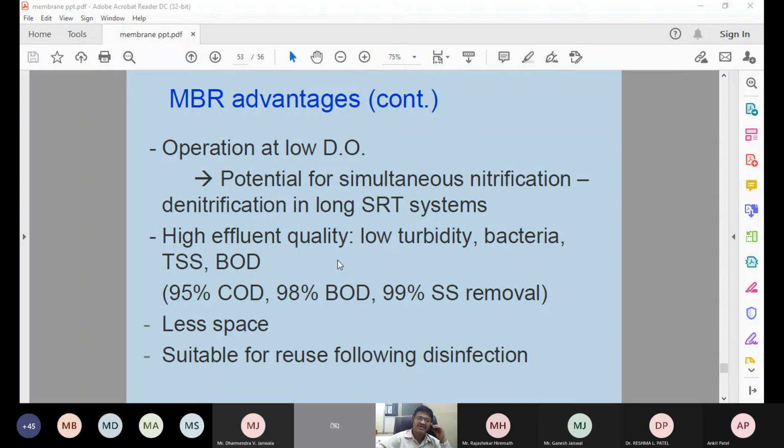The RO system is not advocated. Rather, it will remove the most assimilable form of the alkaline earth metals, which is vital for our body. In the IS standard it is written 600, and if an alternate source is not there, you can go up to 1500 also. That is when there is no other water source, out of necessity.